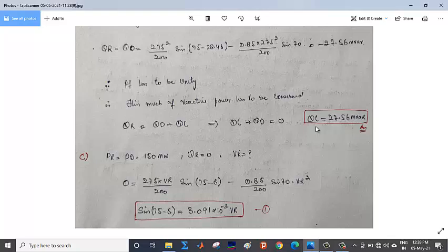We have to design a QL, that is an inductance whose reactive power consumption capacity is 27.57 MVAR. In that case, the power factor will be unity.